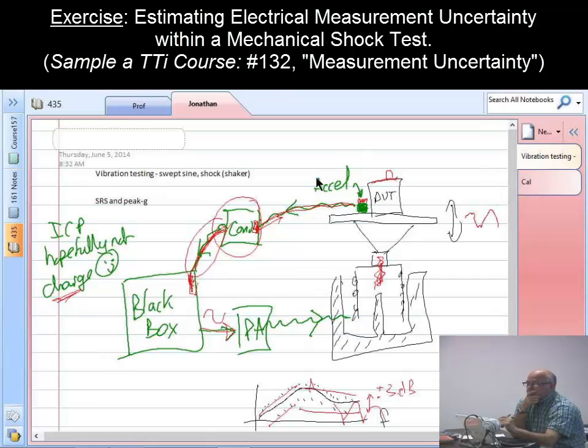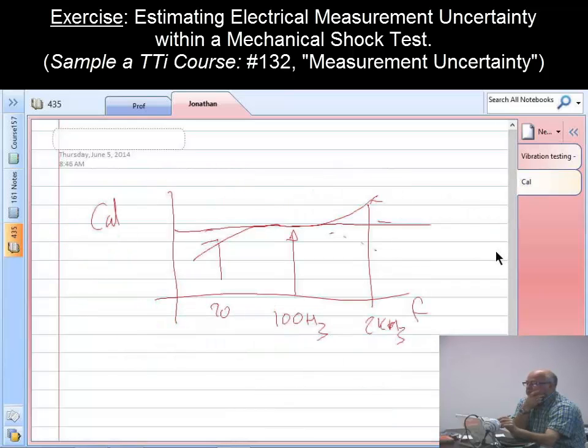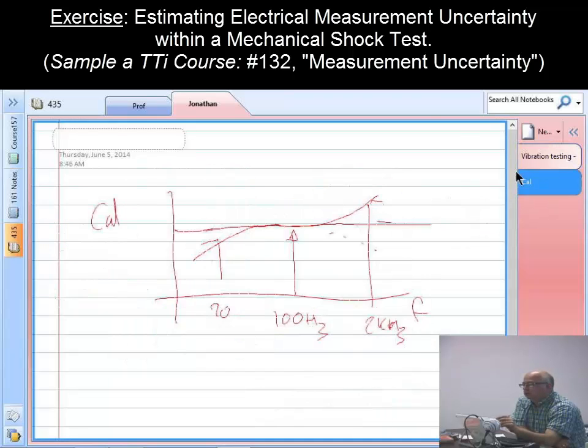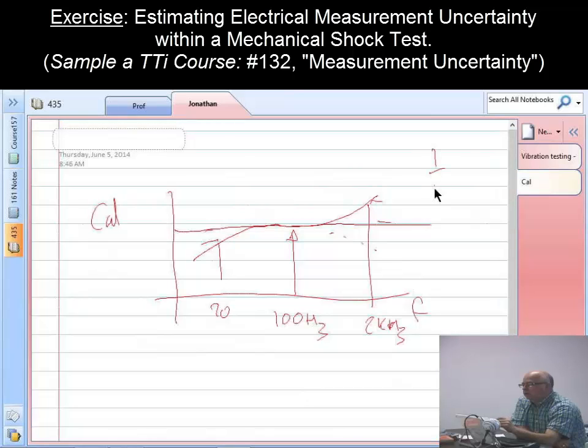So if I had 20 accelerometers mounted onto this fixture, do I have to factor in all 20 of these accelerometers, just going RSS? It depends what the black box does. If it takes all 20 and averages the signal somehow, and then uses that average signal, at that stage you will be using a 1 over square root 20 improvement in the accuracy.